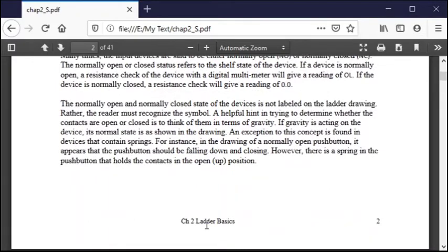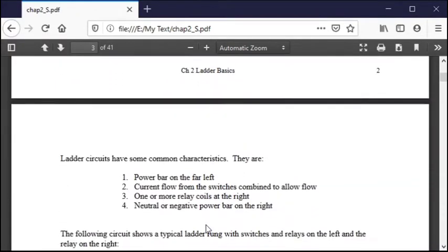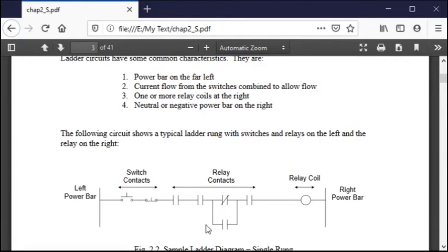There's a basic structure to a schematic, or we call it a schematic or a ladder diagram, and some people call it an elementary diagram, but there's a structure to it, and the basic structure is power starts at the left, ends up at the right over here at a coil or some output device. So these would be considered logic devices, things that make logic happen, and this would be the output device that would actually turn on some device or whatever.